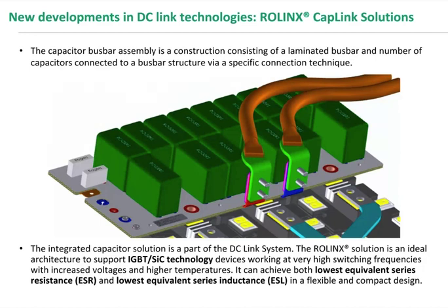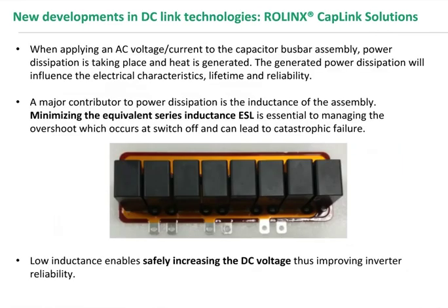We designed the busbar and the way the capacitor terminals are connected to the busbars in a low inductance mode. You will see this a little bit later, maybe not in detail in this free webinar, but at least we will give you some indications. So this is the subject of this discussion. As I said, we are looking at overall low inductance solutions, and as we know, the current flowing not only through the busbars but also through the capacitors generates heat, and overall we want to reduce this heat in order to increase the lifetime reliability of the system.